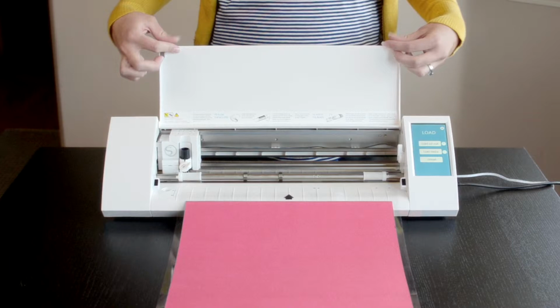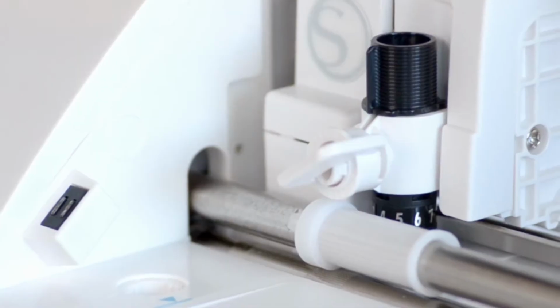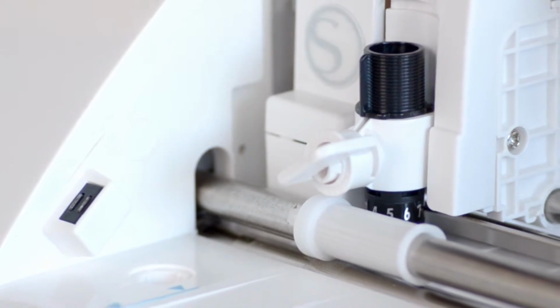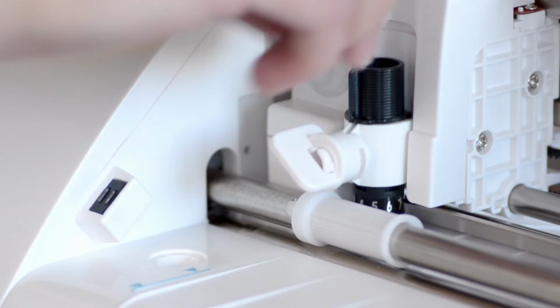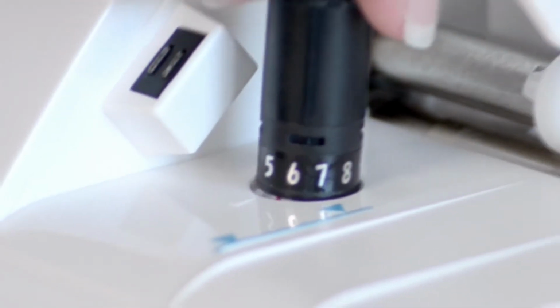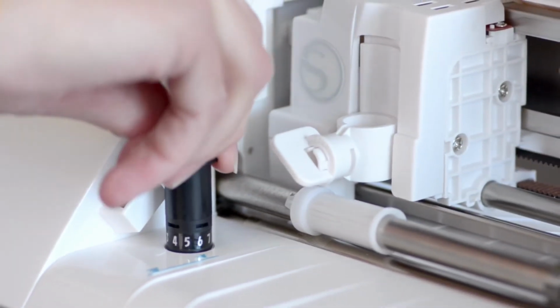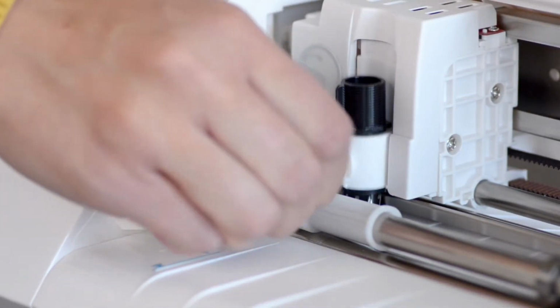You will use different blade depths to cut different materials as directed in the software. Since this example involves cutting cardstock, you will want to use a blade depth of 3. To adjust the blade depth, unlock the blade holder and remove the blade. Place the blade into the adjustment socket so that the arrow on the socket lines up with the red line on the blade. Rotate the blade until the arrow on the adjustment socket is pointing to the number 3 on the blade. Now place the blade back into the blade holder and lock it into place.